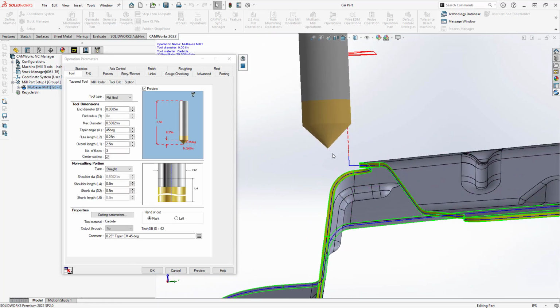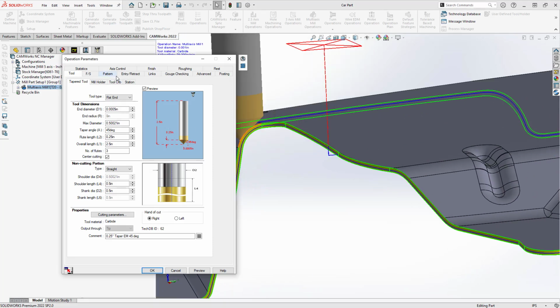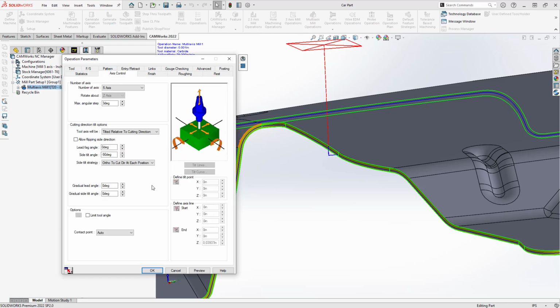But what you'll get when you use this sort of tool is it'll be offset by the diameter of the tool. So the tip of the tool will follow that line, and it'll be offset by a little bit of either my 5 thou or by the full 1/2 inch, depending on how you define your point on your tool. But that means it's just going to kiss that line. Any control we're putting anywhere here currently will just kiss that line. It'll follow that line. You can imagine if you were doing this as a regular 5-axis, you were probably trying to follow that line to trim this part or machine out a surface or whatnot. Deburring actively is gouging the part. So we need to give it a little bit more of a parameter to gouge the part.